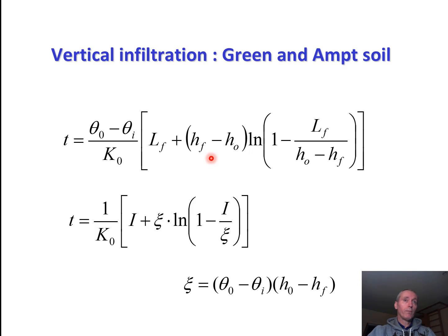To solve this problem, soil physicists introduce a weighing mechanism to define the suction head at the wetting front between the very large and the very small suction heads before and after the wetting front. They suggest to use either the conductivity or the diffusivity function to make this weighing. This is explained more in detail in the following Python notebook.